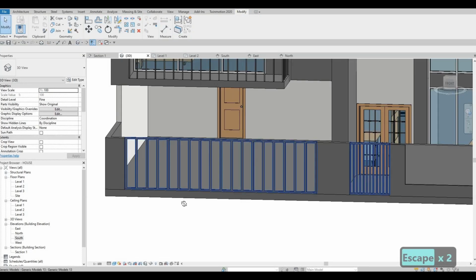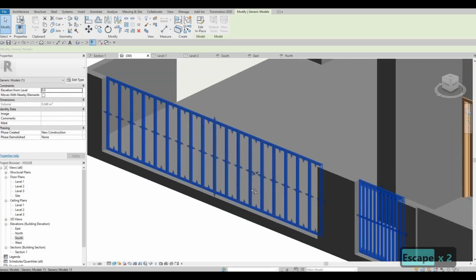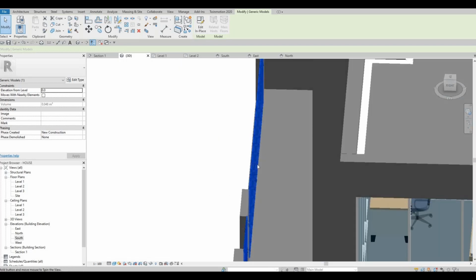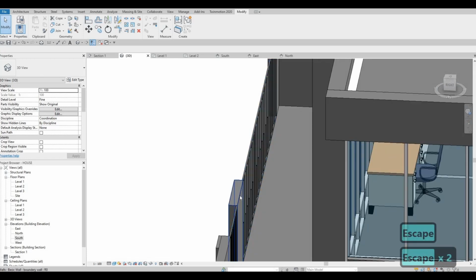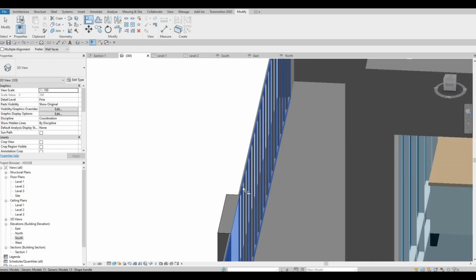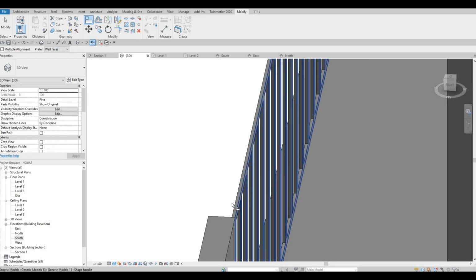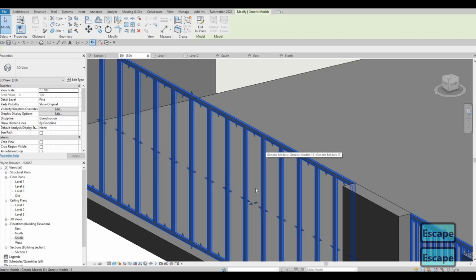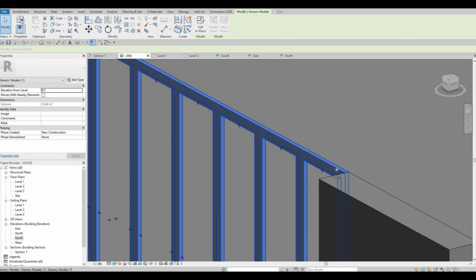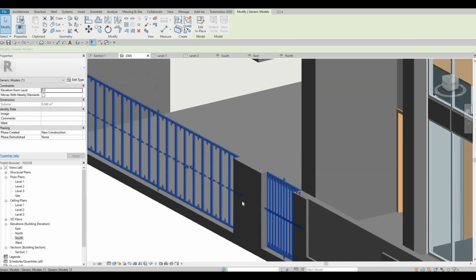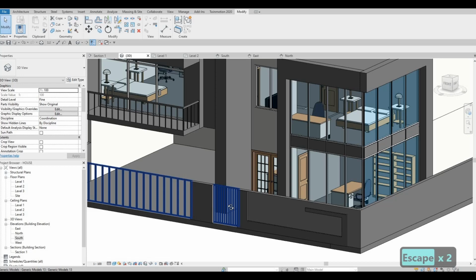Okay. And then after that, you just need to extrude it. So what I did, extruded from this face. So you could use align, AL, choose this back border wall, and then this at the back as well. And it will align. And then here, I'm just going to select it. And then I just push it backwards and then creating this thin gate. So basically, that's what I did.